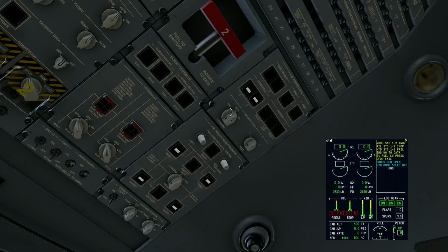This airplane has automatic anti-icing, so you don't necessarily need to be turning it on and off and on and off like some other aircraft, but you have to understand how the logic works. In auto mode, that's the default mode for this knob, the ice protection system is controlled by the ice detectors, and there's a scheme they follow. Essentially when they detect ice and the scheme is followed, it will open, and you'll see an open inscription in the anti-ice valves. You'll also see an ice condition EICAS. And that is the airplane saying you're in ice conditions, we've detected ice.